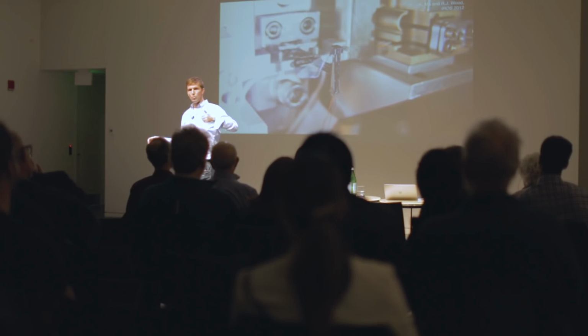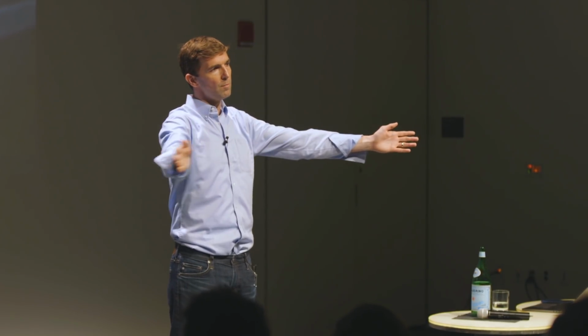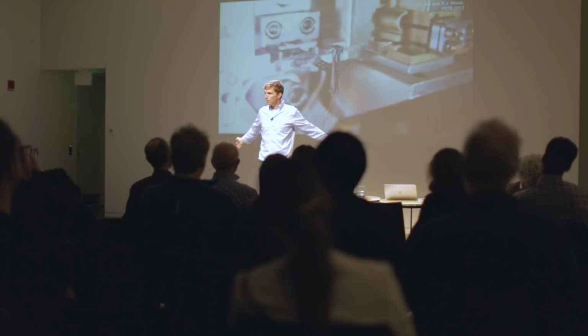And so then I can do force modulation independently on each wing to create body torques. The way I do that is, if I have a larger amplitude on one side than the other, then I have a larger force on one side than the other, so I do this, right? And if I sort of bias my motion fore or aft with respect to the center of mass of the robot, then I get a pitching motion.